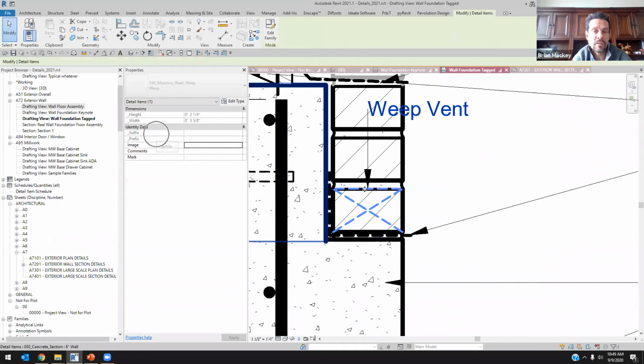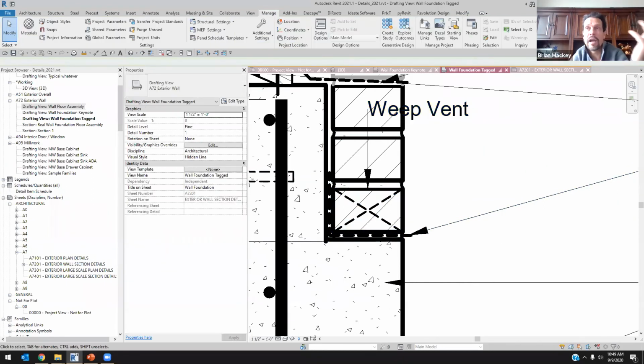So you'll see suffix and prefix are there. That is a custom parameter nested into the brick family. I cannot change those. So any custom shared parameter I use, I don't use for everyday tagging because if they're nested into something else, I can't tab select it to get it. So I do use type comments. There really is no difference between type comments or description.